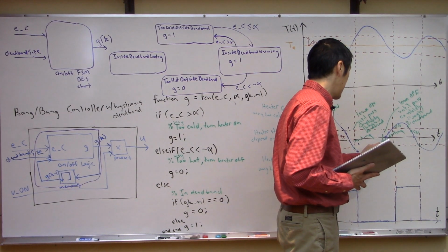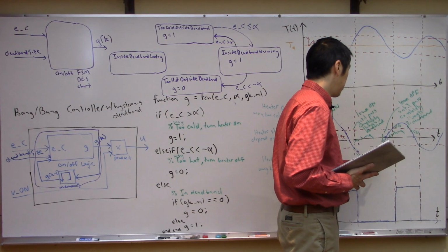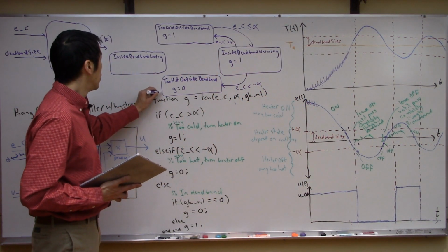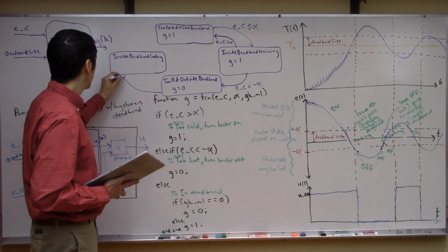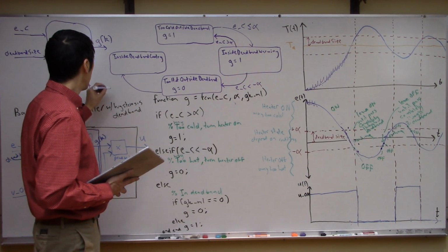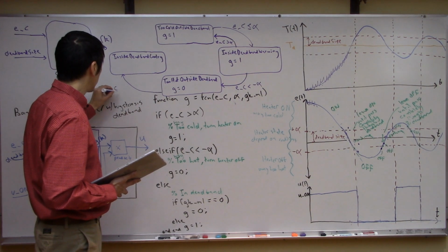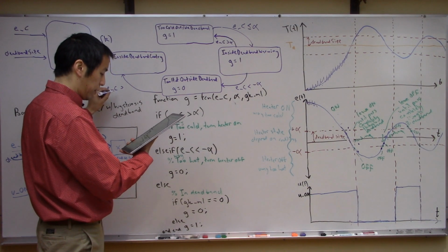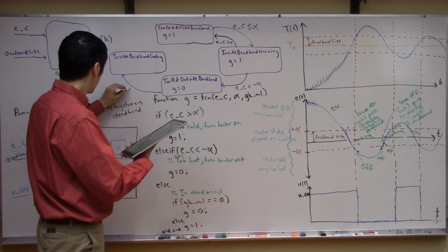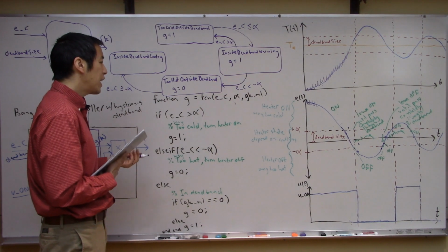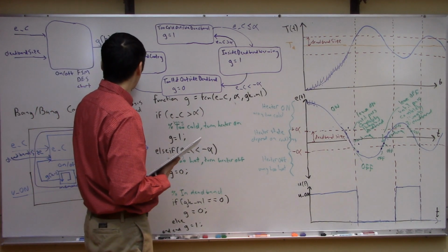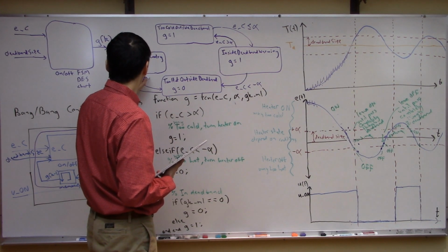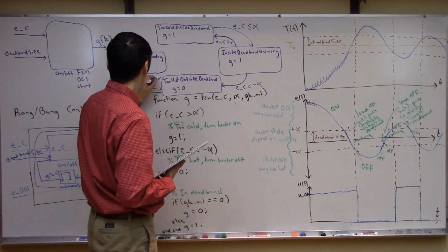You're over here. And then again, we're right here. You could bump yourself now into the deadband on the cooling side. So again, we can just say, all right, we're going to allow a transition to go from here to here, right? And this occurs when your error signal, what is it? It's greater than or equal to minus alpha. Okay? And again, for giggles, we could allow ourselves a transition back, okay? When your error signal is less than minus alpha, you could go back here.